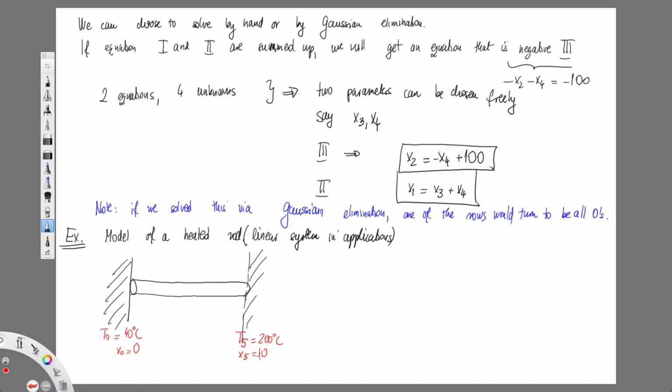Okay. So these ends are held at constant temperature. And I'm wondering what is the distribution along this rod. And distribution would have been simple if I actually didn't lose some. So if I had a completely isolated system, I would, give or take, have a linear distribution in between. Okay, so I could just do a linear. But I'm losing some of the heat to the ambient temperature.